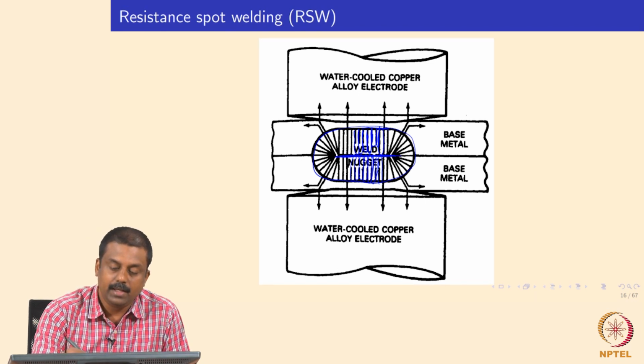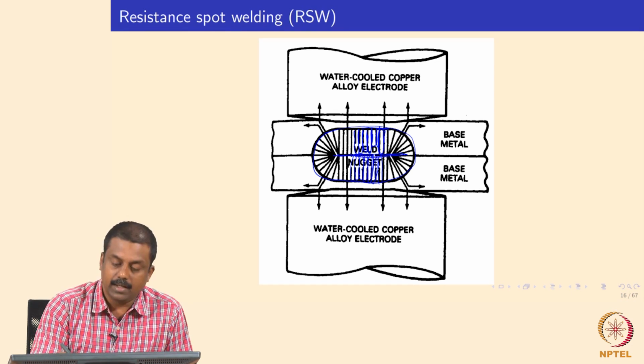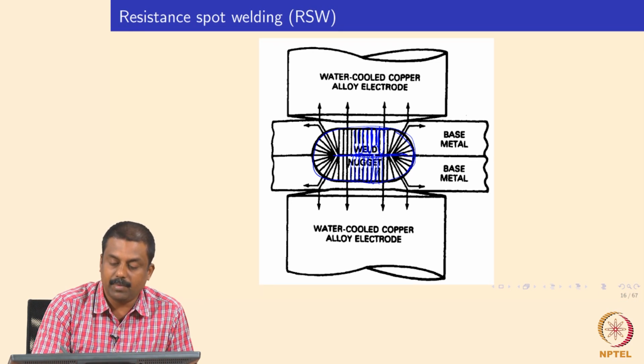Because of that, the solidifying grain boundaries and the weld center line would be enriched in alloying elements, making them very brittle. So apart from the segregation and the columnar solidification, at this location you also have a weld boundary and unwelded sheets that act as stress risers.